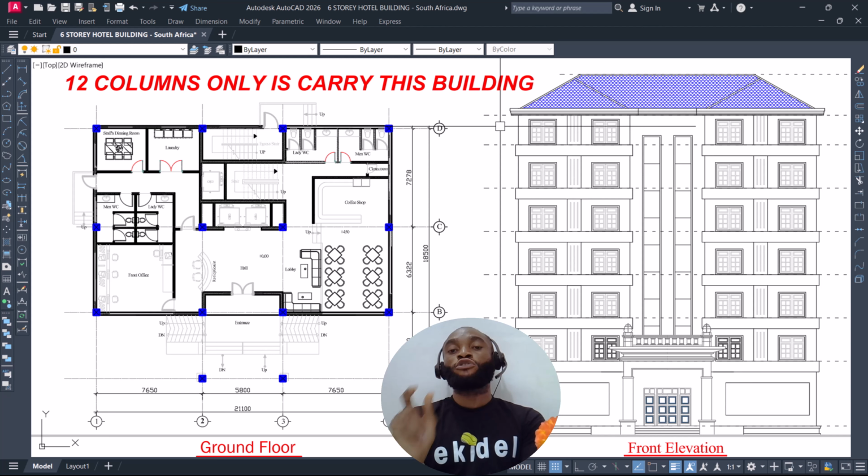and then going for the foundation design, where we used a raft foundation for this particular 6-story building. Now, the reason for using the raft foundation is because of the properties of the soil, the soil test, and the bearing capacity. So it was a raft foundation that was suitable. In the course video, you will also learn how to choose the type of foundation for particular structures.